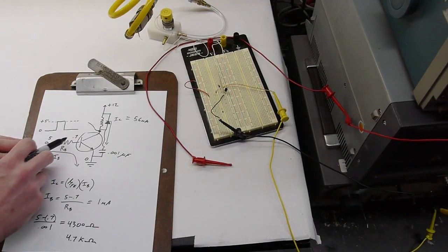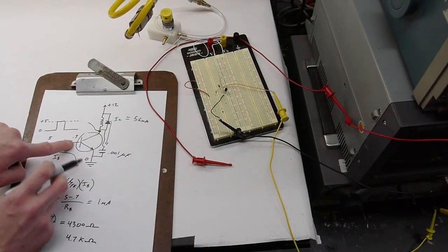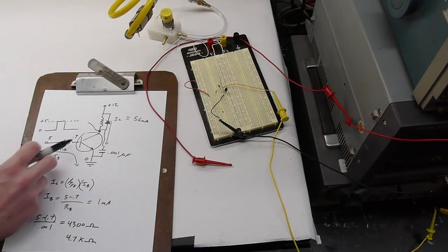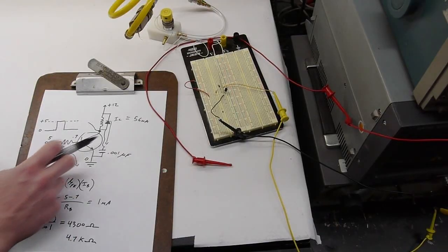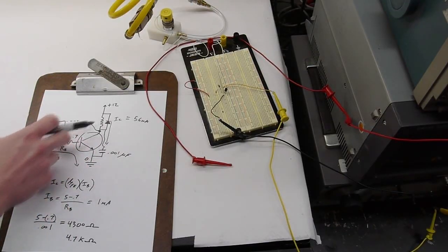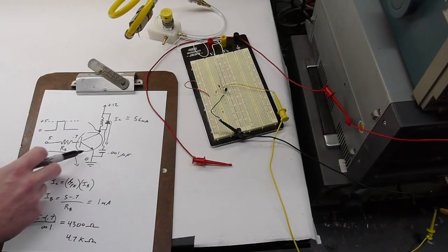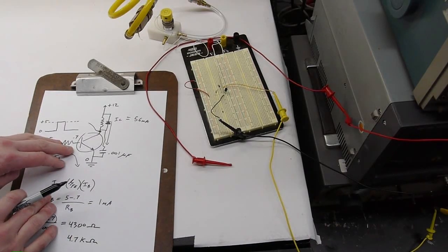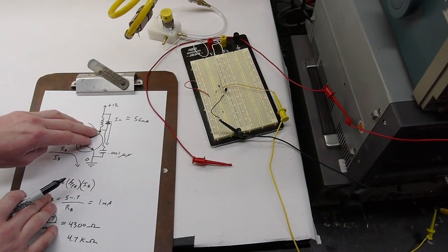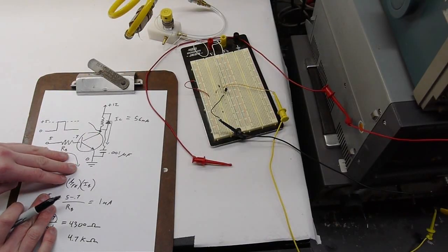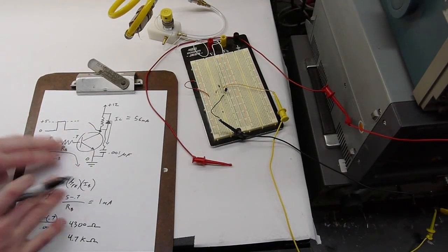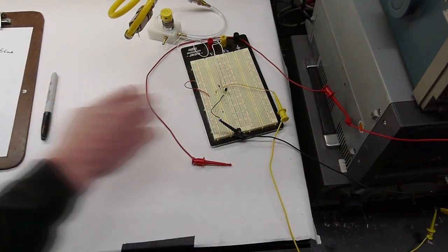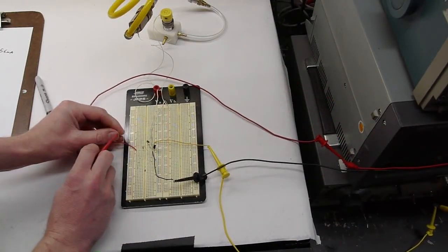So I said that the reason we have a 0.7 volt drop from the base to the emitter is because that's the way silicon semiconductors are built. We've got a p-n junction here. From the collector to emitter, there's a p-n and an n-p junction, so that 0.7 volts cancels itself out. So if the transistor is perfectly built, the voltage here will be 0 when the transistor is fully conducting. But you know, there are problems in manufacturing, and I think they might even build them asymmetrically on purpose or something. So actually, let's measure it and see what we've got.